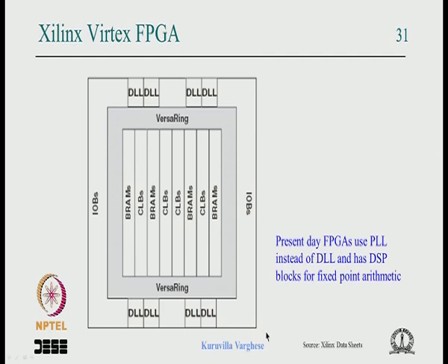There are many things to look at in the FPGA, like the programmable interconnection and these logic blocks. But if you take the memories, they come built in, and you have a tool to instantiate them in various widths and depths and so on.